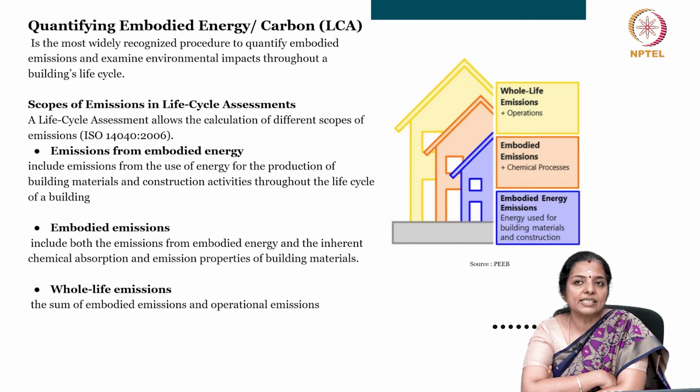Embodied emissions, for example: cement is produced through the decarbonization of limestone, and this chemical reaction emits carbon dioxide, while wood absorbs carbon dioxide during its growth. So, whole life emissions is the sum of embodied emissions and operational emissions from energy consumption for the operation of the building and its appliances over the entire life cycle.